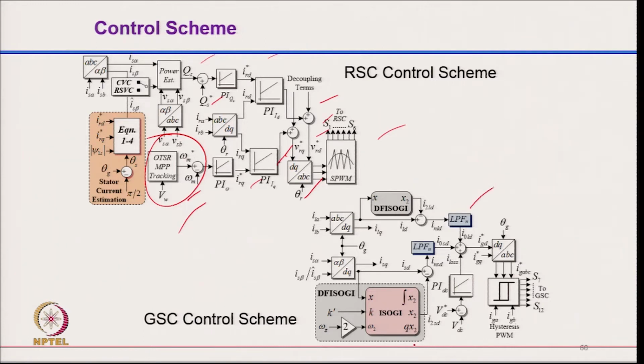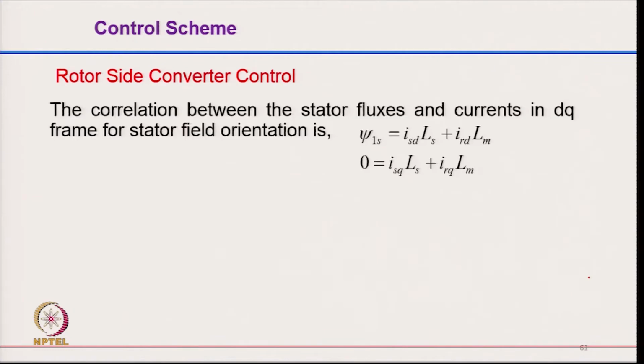Here we have the responsibility of the DC link voltage control, I mean the reference DC link voltage, and you can generate even the desired reactive power required at the grid side if you really need. Again from vector control we are able to get a 2 axis current. We can have reactive power, otherwise we can have only the active power for regulating the DC link voltage, and these are the grid reference currents, and we have the sensed grid current, so we get the signal for that.